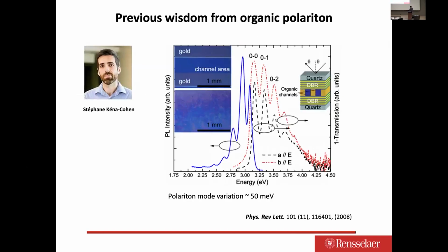So at one of the MRS meetings, I met one of my friends, Professor Stephen Cohen, who did his PhD work with Stephen Forrest at Princeton, and later at Michigan. In their early work in Physical Review Letters, there is an interesting thing he demonstrated: essentially a pre-made cavity mirror, using gold as a spacer, and eventually a metal-metal fusion bond to bond these two mirrors together, forming the organic material in a channel and eventually making a single-crystal organic inside a pre-patterned nano channel.